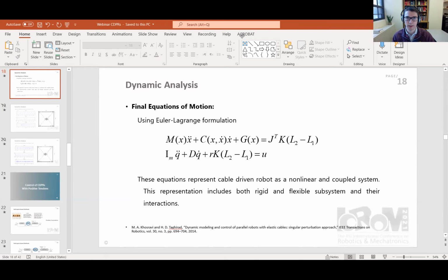I was wondering, though, if you just commanded very simple motions that weren't very dynamic, would you be able to actually estimate all the parameters you need to be able to converge your estimates there? The convergence of a nonlinear disturbance observer is necessary, and the speed of the convergence of the NDO should be greater than the bandwidth of the control loop. Yeah, okay, that makes sense. Thank you. All right, thanks.